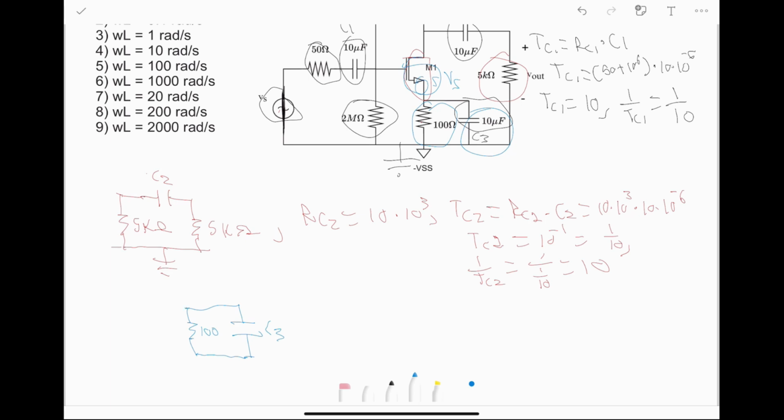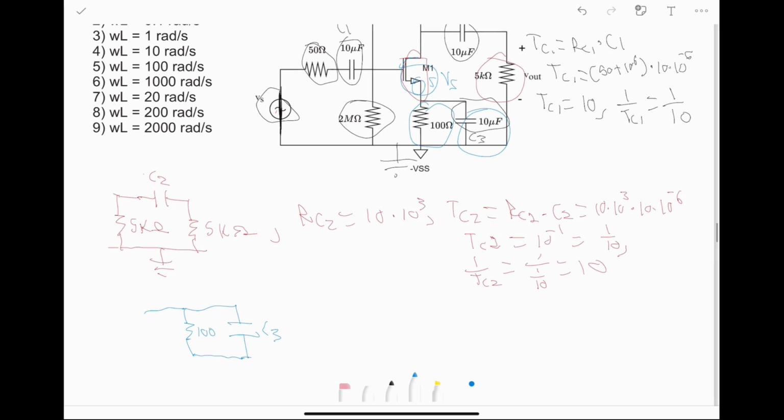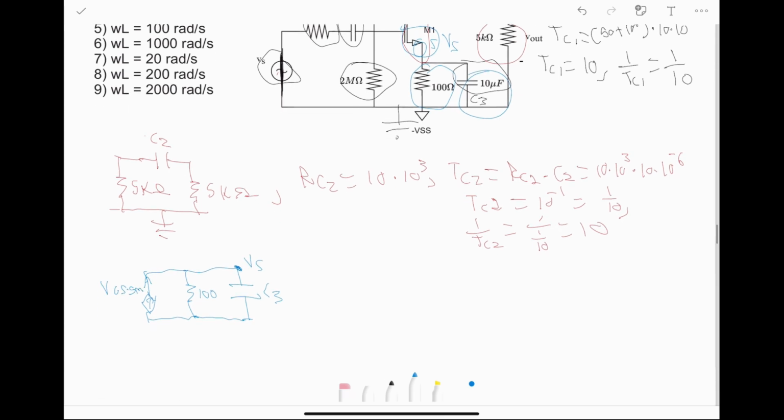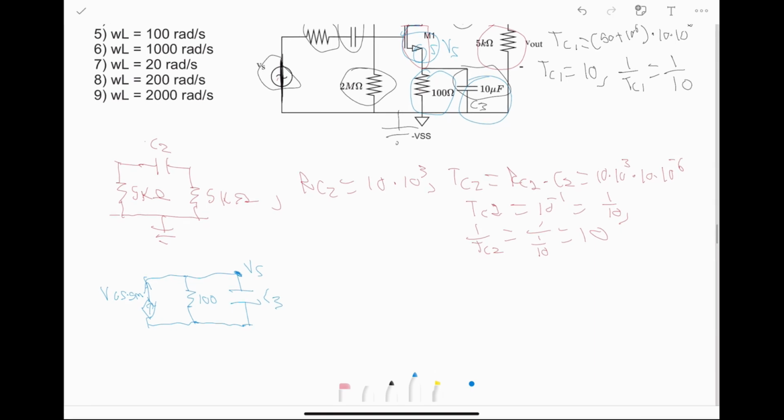And remember that if we draw this dependent source, the current going through this branch is VGS times GM, and now this point is actually equal to Vs right here. So the Vs matters now, and it is creating some complexity, which we can solve by doing an IV test that you learned in 2K1.